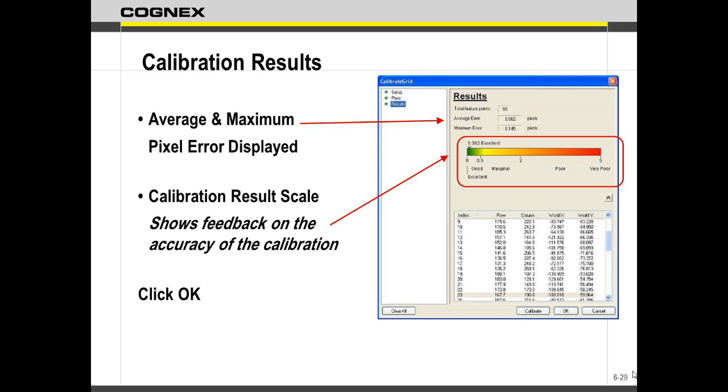Don't think the camera's acting bad. In fact, the camera's acting good. We started finding this out when we got to the 7,000s, which is almost twice the resolution of the 5,000s we were using. All of a sudden we started coming up with marginal. I used to have excellent. Now I'm getting marginal, and that hurts my pride. But as we look at it more, it's because they're far less forgiving of a poorly printed calibration plate.